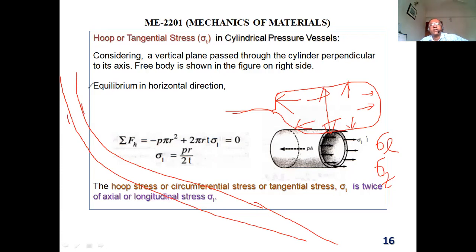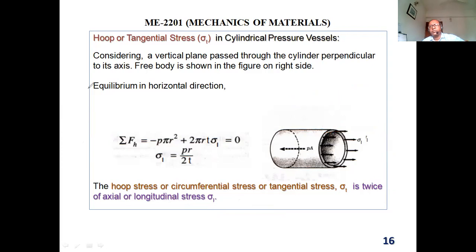So when you pressurize a cylinder, we need to figure out how much the radius will increase. If you have the option, you can measure the diameter of the cylinder before and after pressurizing. If you just wrap a tape around the cylinder, you get 2 pi r. That will be the initial peripheral length, say PI.